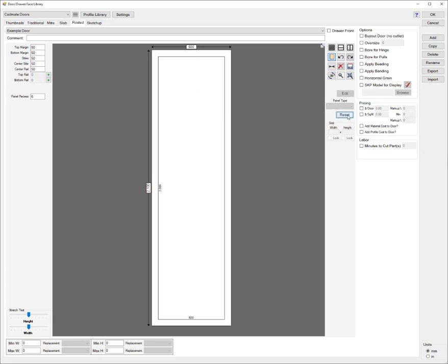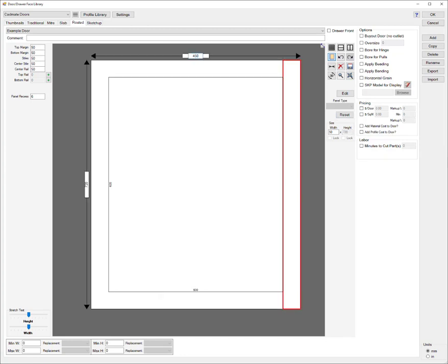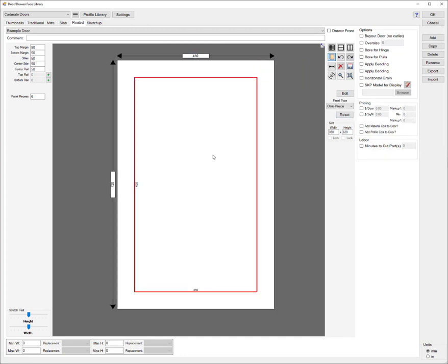Let's go ahead and reset this door, and I'll change the overall size back down to a standard height. Now let's take a look at changing the shape of the middle section. Let's click back in the middle opening here and change this to be a pocket again. I'm then going to right click and choose Select Special Mullions. Let's change that to a double bow. I'm going to leave the input of the mullion width to be half the size of my rails. You can change that to whatever you like.